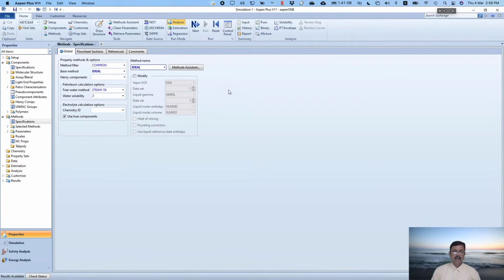Yes. Now you can observe over here the analysis is binary analysis. So here you can generate TXY, PXY, and free energy mixing curves for a binary system. So we will try to find out the vapor-liquid equilibrium for the benzene-toluene binary system. So let us click over here.